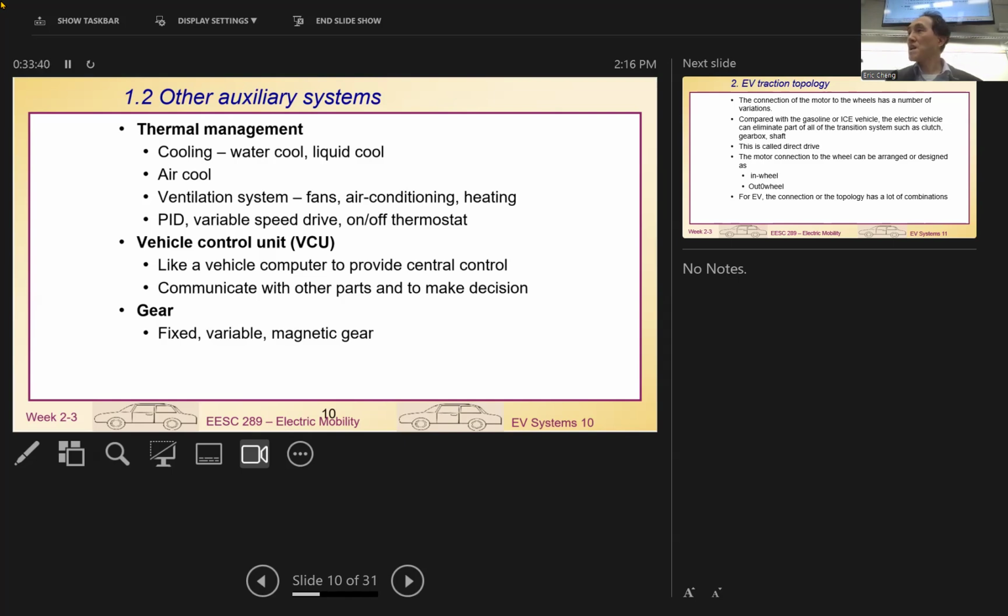That PWM uses high frequency, usually in the tens of kilohertz. Just like with your motor, we ask you to do high frequency operation because the harmonics will be really high frequency. The higher the frequency, the worse it gets. The higher the frequency, the more iron loss you get, and the poorer the efficiency. So for this kind of Tesla motor, whatever motor they use, we have high frequency and high power there, but they're still so small.